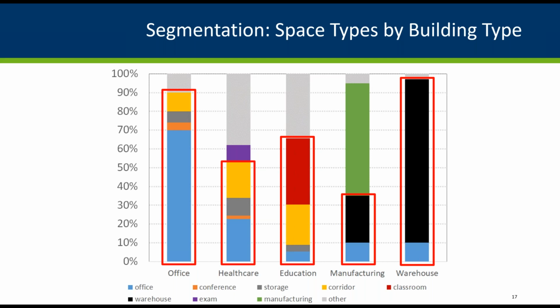Open plan offices are ideal for adjusting light levels because the light levels and associated electrical power make up a larger portion of the total building lighting power and can be affected with just a single adjustment. This minimizes the time and cost of achieving savings. Other good candidates are space types with many similar spaces, such as private offices and classrooms, where the amount of light level adjustment can be determined in one space and then quickly applied to other similar spaces.